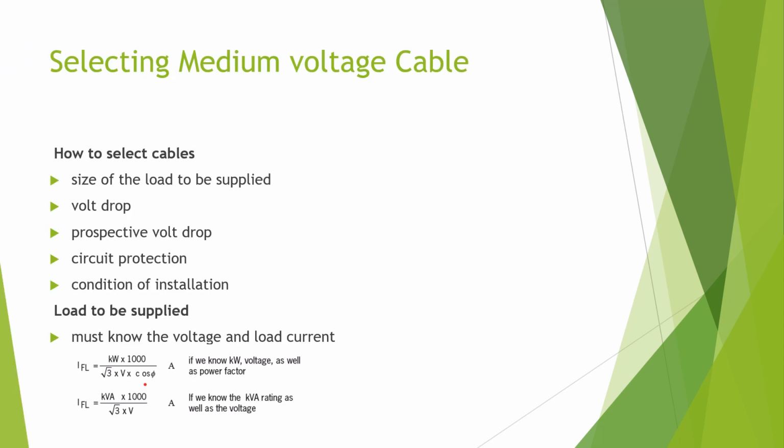Selection of medium voltage cables. How to select a cable. What's important: the size of the load. We must know the volt drop, calculate the volt drop, the prospective volt drop, the circuit protection, and the condition of installation.